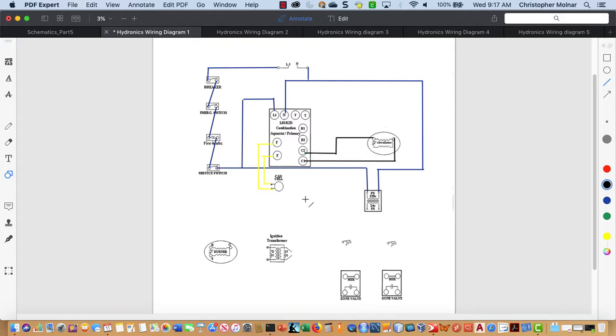Okay, so we have a few terminals left on here. We have a T and T and a B1, B2. Let's go ahead and get my burner, which is the B1, B2. That's my burner. Because we're not being told otherwise and we don't have additional terminals, the burner motor and the ignition transformer have to energize and de-energize at the same time. So let's go ahead and get that out of the way to start with.